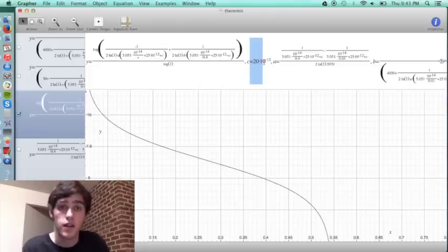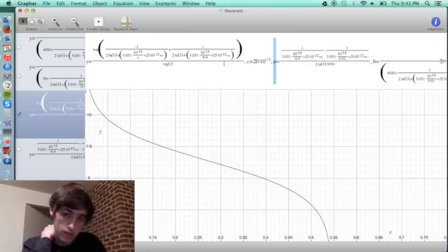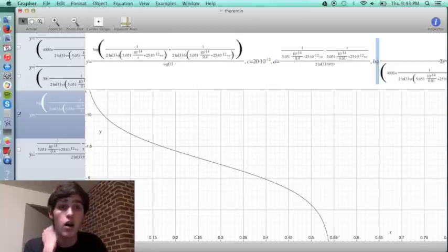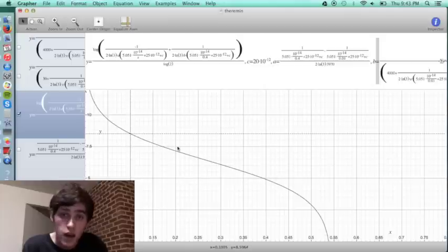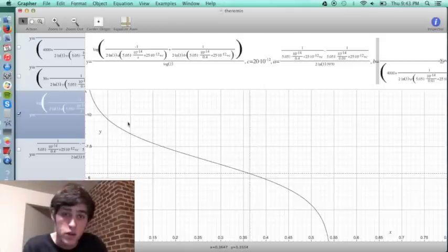So from that, I define this C value, and then I define the resistors R and R1, R of the pitch oscillator and R of the reference oscillator. And when you evaluate all of this, you get a frequency that ranges from 44 kilohertz to 48 kilohertz. So it's very specific. And this is the linear part of the graph that we're concerned with.